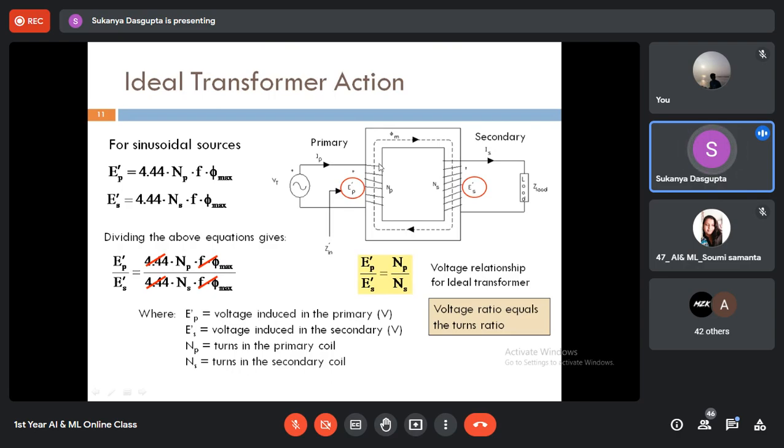There will be a drop in the windings. Those are called ohmic drops. And based on these drops, the ohmic losses will be generated. Those are called copper losses because mainly these windings are made of copper. Fine. So in an ideal transformer, these losses are totally absent. The windings serve purely as inductance, right? And with a pure sinusoidal voltage signal at the input side of the ideal transformer, we have seen already